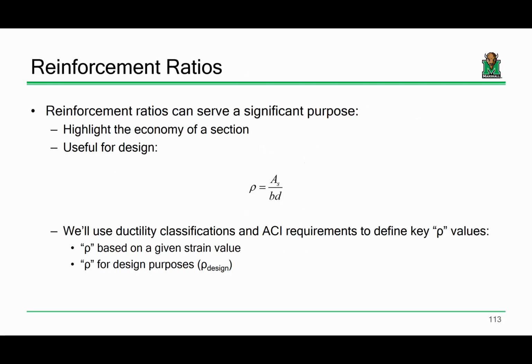So what do you use for rho? Well, rhos, again, they're really important, okay? It's a new term, and I know this is the first time that you're seeing it, but rho values, or reinforcement ratios, if you ever hear me term the reinforcement ratio, they are very, very important because they are essentially the primary tool that we will use to select reinforcement patterns in reinforced concrete beams.